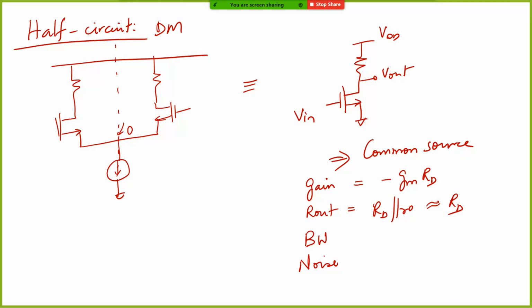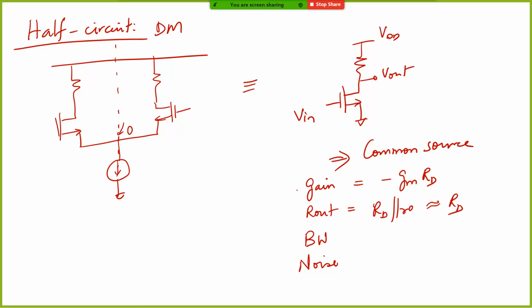And all the small signal analysis that we did in the previous module for common source amplifiers can be basically reused here. Therefore, you can also have the other variants that we talked about. The same thing happens if you try to increase RD in order to improve your gain: you end up with a crunched voltage swing at the output. The V out common mode is nothing but VDD minus ID RD, or I tail by 2 into RD.